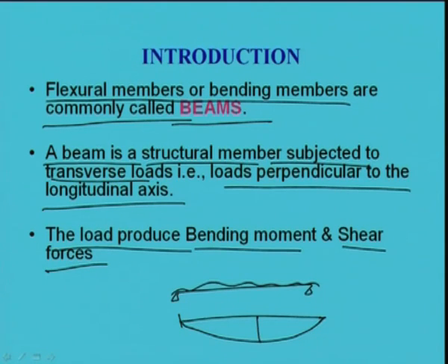So, this will be the bending moment, here the maximum moment will be developed as per the loading condition, and also shear force will develop. Shear force will become something like this. I will come to it later in detail. So, one is bending moment coming into the picture, another is shear force. With these two we have to design.